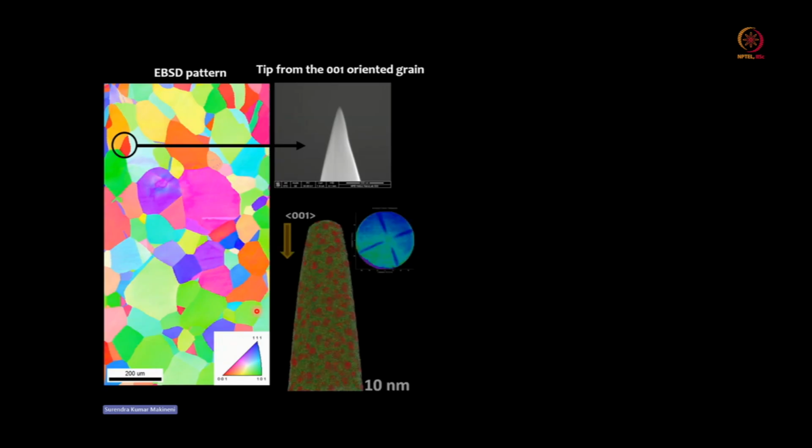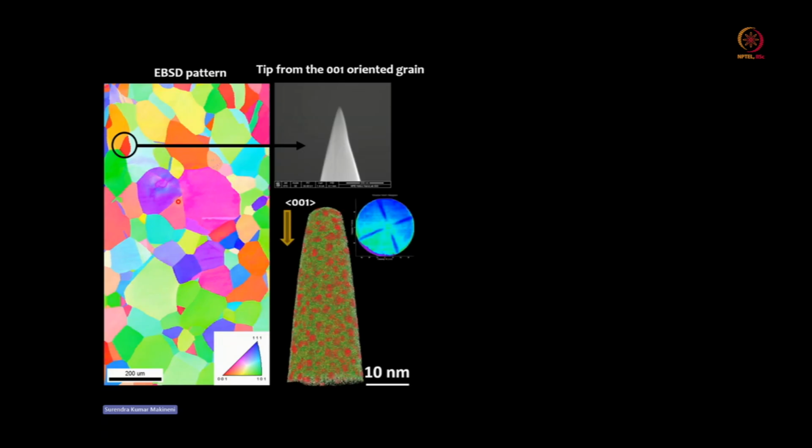You make an atom probe out of plane sample. You field evaporate it. This is a copper sample which has cobalt precipitates. These are coherent, and you can see that along this direction in these maps there is a cobalt clustering in the copper matrix. Copper is a green, golden color, and the red color is